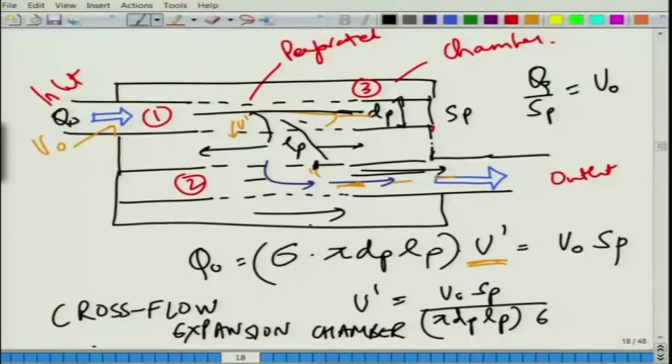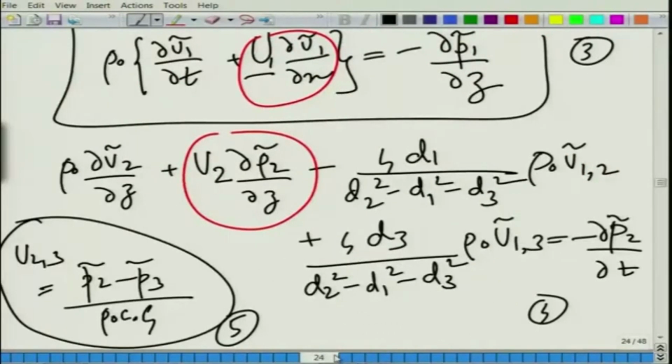So, in all these expressions that you are seeing, wherever we consider perforate impedance, we consider it to be uniform throughout the cross section, because porosity is assumed to be uniform and the hole distribution pattern is assumed to be uniform, but it need not be. If we have a non-uniformly perforated pipe, it will have its own effect. For such a case we can consider a slightly different segmentation approach.